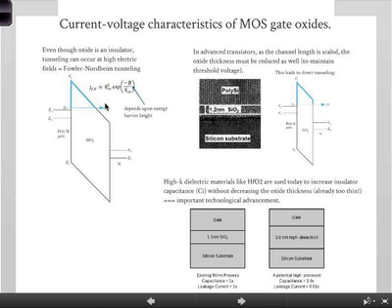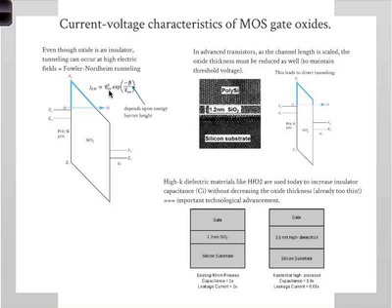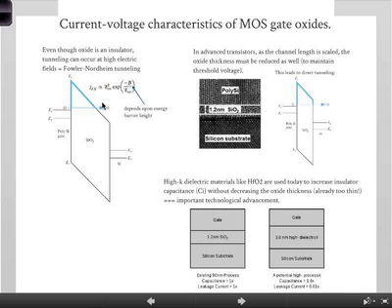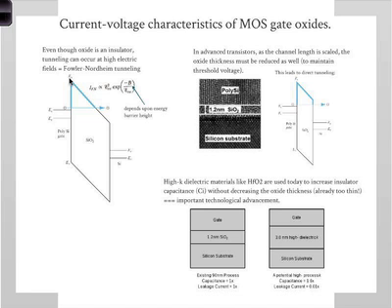Okay, and this idea is called Fowler-Nordheim tunneling, and you don't need to understand how it's derived, but it's a quantum mechanical tunneling, very similar to what we talked about before, and it's proportional to two things. First, it's proportional to the oxide electric field, which is obvious, right? Because the more the electric field, the more it bends, and it becomes easier for the electron to tunnel through. It also depends upon the energy barrier height, inversely dependent, inverse exponential. Okay, so that's a little bit common sense.